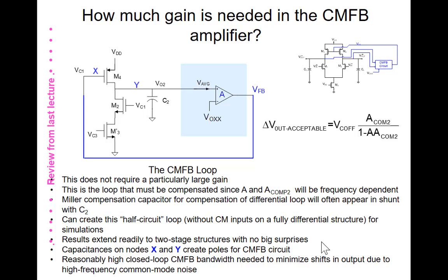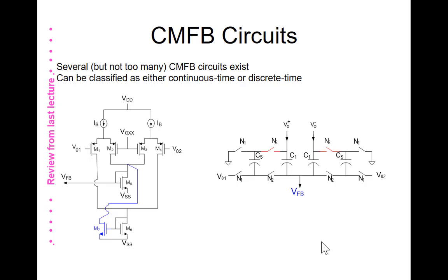If you take two resistors and drive them on the two sides, the voltage between the two resistors is the average of the two voltages. So the averager circuits are usually real simple. I don't see very many common mode feedback circuits published, and I'm not exactly sure of the reason. Maybe one reason is we can get by with a small number of different common mode feedback circuits.